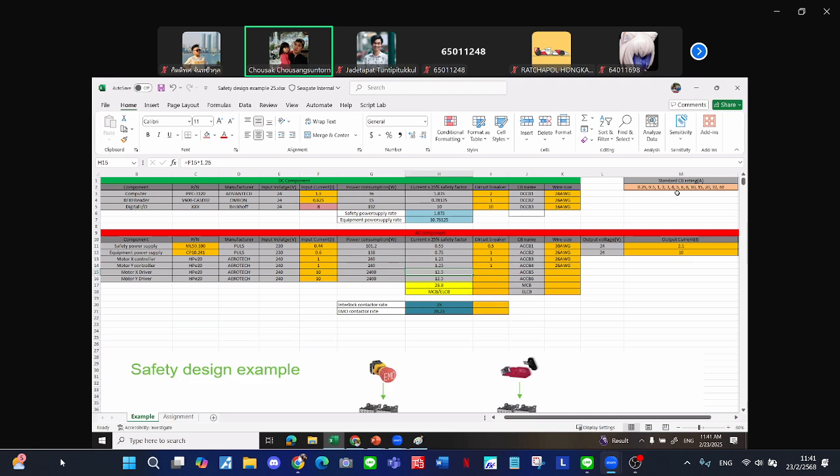And the last one, 12.5. The closest is between 10 to 15, right? As I mentioned before, I use 10 ampere, which should be enough if you compare with the normal current, it should be enough to control this one. Okay. You can use the 16 AWG for this one. And this one comes out with the MCB and ELCB rating.